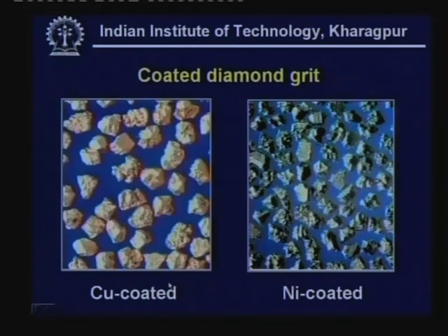So far we have discussed the uncoated grit, but now we have some grain coating. With this grain coating, the whole idea is to enhance the performance of the grit under a specific application. Now, for grinding of cemented carbide, normally dry grinding is recommended. It is just to avoid differential cooling in the cemented carbide. It is safe to have dry grinding rather than to use unreliable, non-uniform cooling. But in that case also protection of the grit is very important.